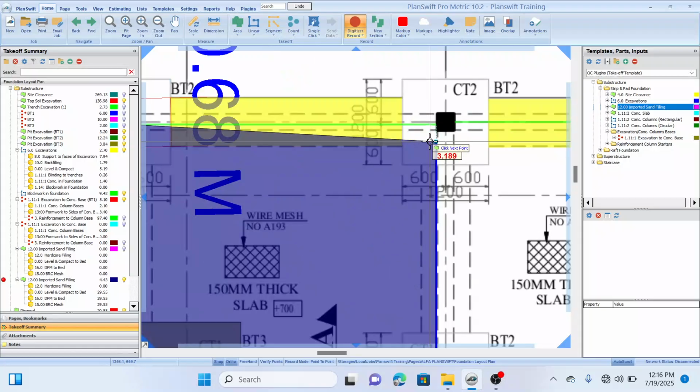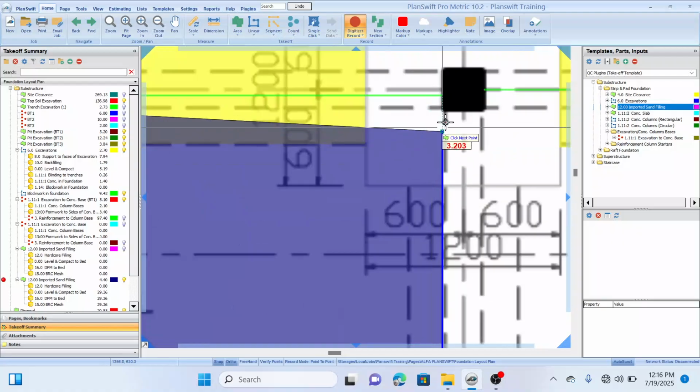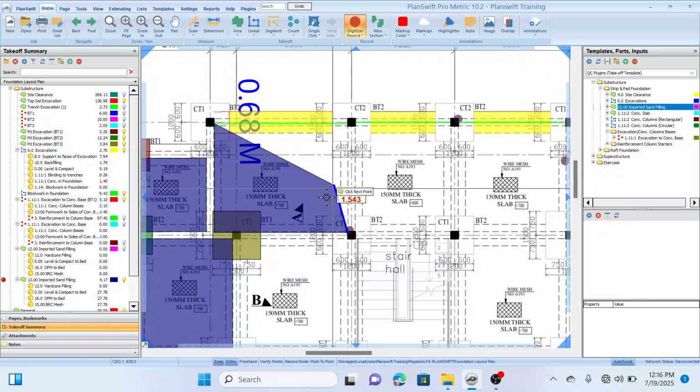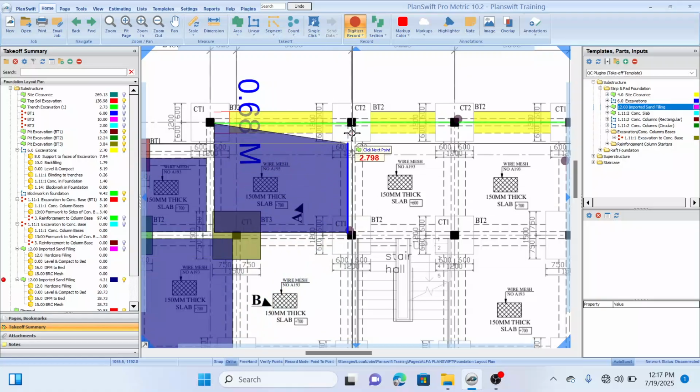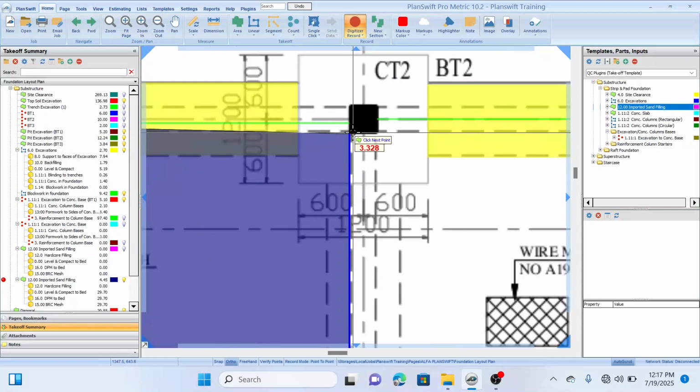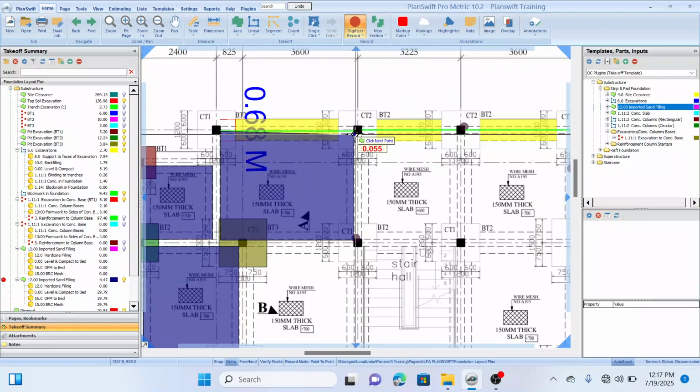Since it's automatically predicting that point and that's not the right point, you can turn off that prediction by clicking on the snap at the bottom. Snap. If you switch off the snap, it won't predict the points for you again. Okay, so I'm going to click on escape here and end my measurement.